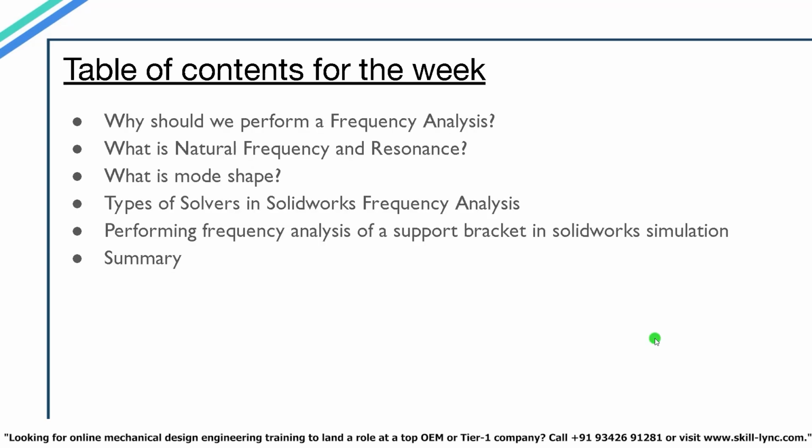Hey guys, so in this video we will be discussing why we should perform a frequency analysis, and after that we will discuss what a natural frequency is and what resonance is, and once that is done, move on to discussing what a mode shape is.